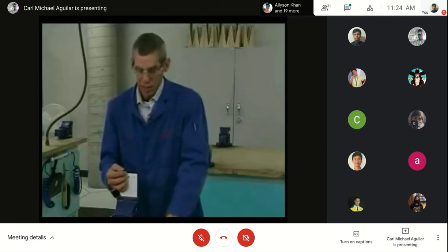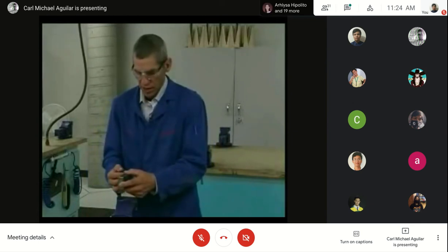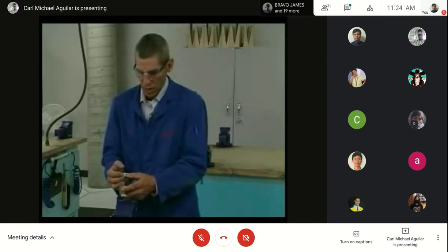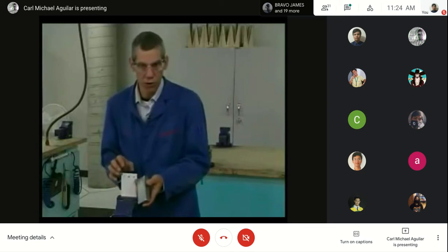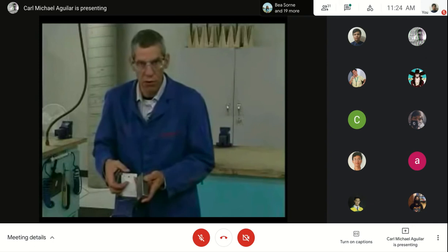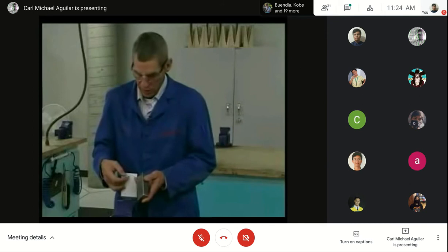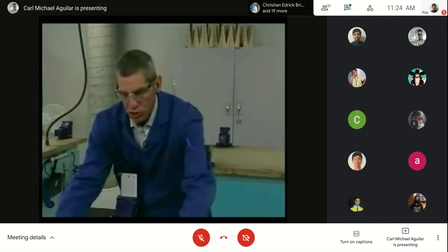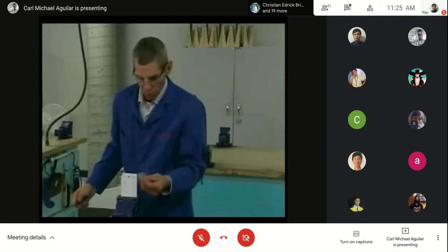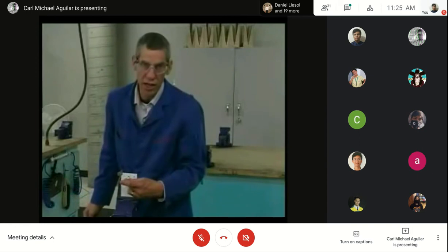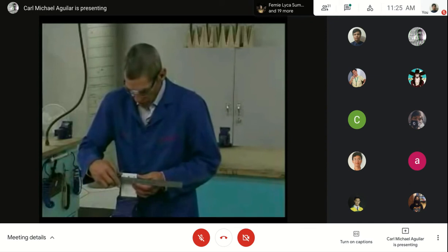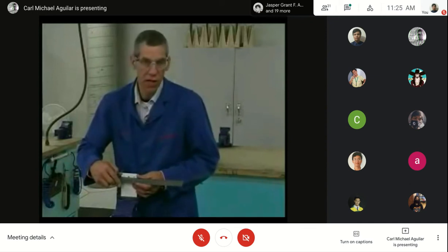The shop head can get damaged by the bucking bar sliding off part way, causing a mark on the shop head. The shop head could be undersized, meaning it hasn't achieved full diameter. And remember, the diameter of the shop head needs to be 1.5 times the diameter of the rivet. So for a 5/32 inch rivet, I can check the diameter by using another rivet, sticking it beside, seeing that it's greater than 1 diameter, but less than 2. Or I can use a ruler, and measure the diameter across the rivet.